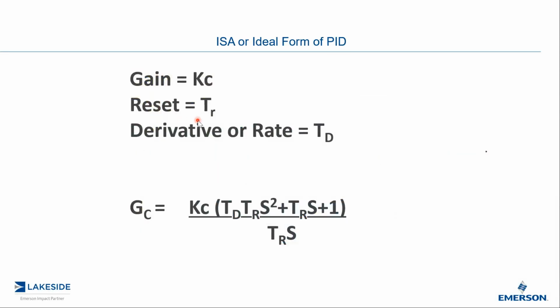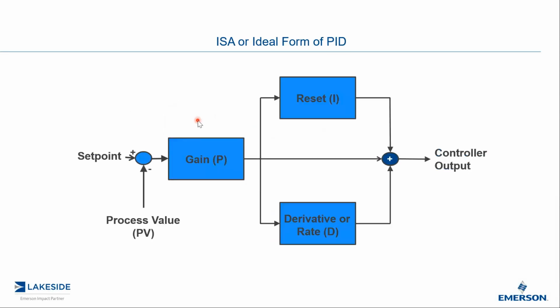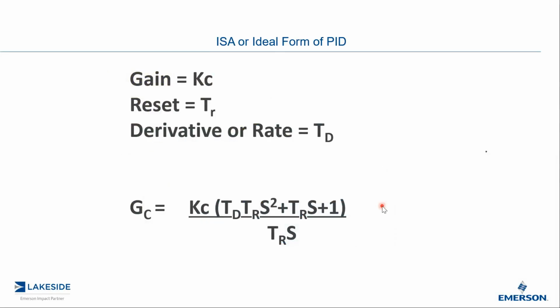So let me go back. So after that, the proportional part goes straight through. You got the integral action or reset and derivative or rate go this way here. And yes, there is an actual Laplace transfer function there, and that's the actual Laplace transfer function for a PID controller right now.